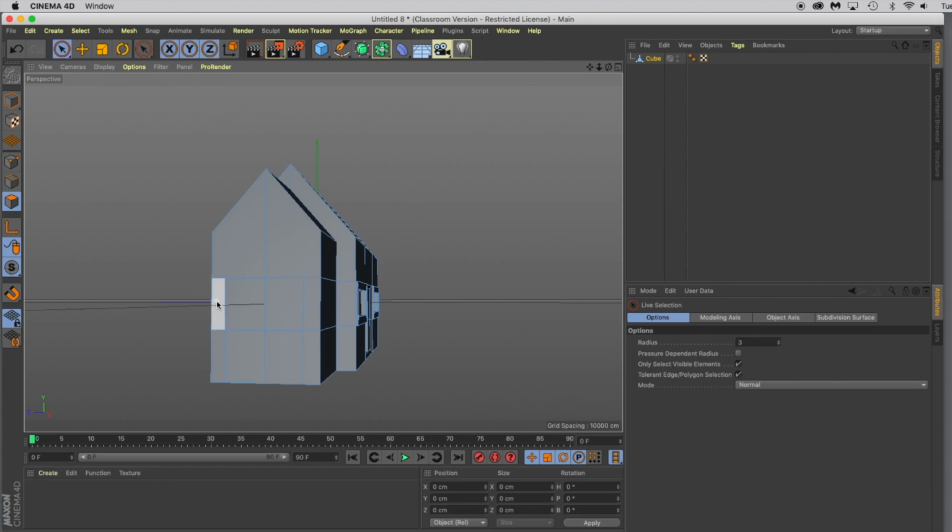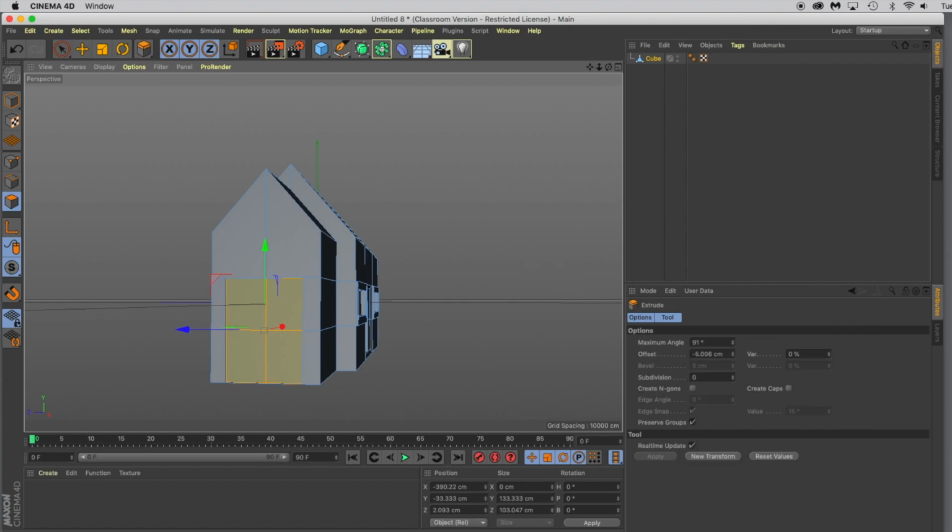And that will work. So now we have some geometry that we can make a little quick garage door with. So I'm going to select those polys, holding shift, hit D on my keyboard, and we're just going to extrude this inward a little bit so there's a little bit of a lip. And if you want to put a casing around it, you can take the knife tool and just cut out a casing, but that will give us a little feature, and that looks pretty good.